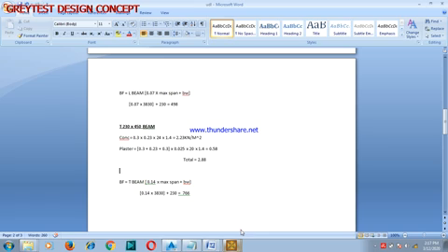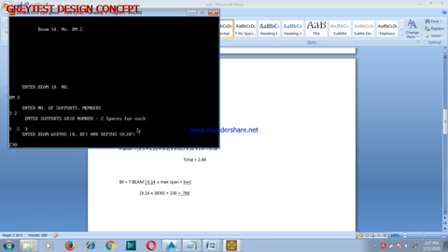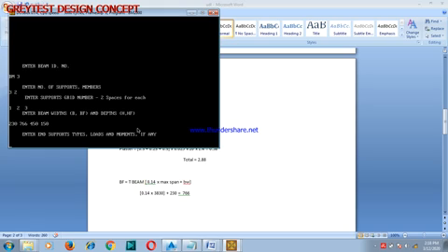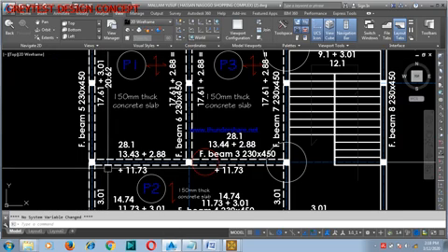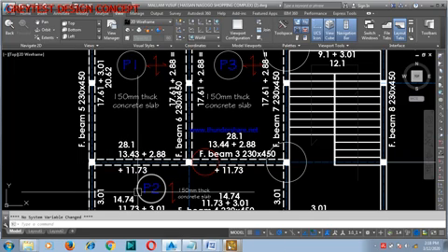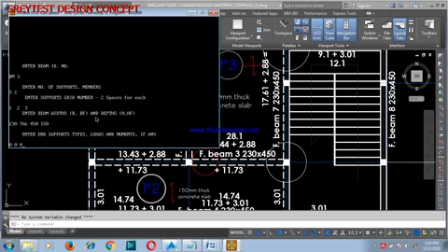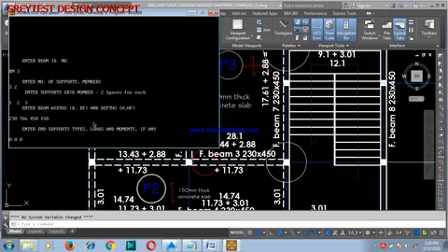So our value is what? 766 for T beam. Okay, 766. Then your depth is what? 450. Then your height of flange is 150. Then you enter. Now enter end support type. Okay, 000. I believe you understand where we got this from. We said there is no load on it, so there will definitely be no moment. And then the type of support, is it fixed, built-in, or rest, on both the first support and the last support.